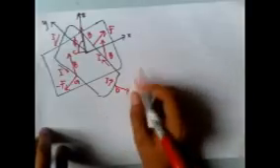The wires leading the current into and out of the loop and the source of EMF are omitted to keep this diagram simple. The direction of our current is in that direction. The force F on the right side, of length a, is in the x direction, and on the opposite side the force is negative F. The force on this other side we denote F prime, and this one is negative F prime.